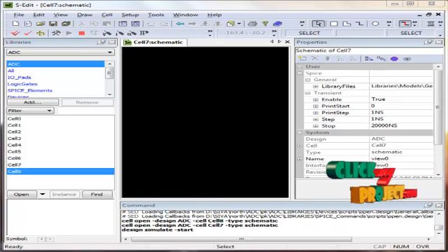Initially, the input digital word is given to a multiplexer circuitry. Depending on the logic value of each bit of the word, the multiplexer chooses the particular voltage to which the capacitor is to be charged. If the input bit in the digital word is logic 0, then the multiplexer chooses the input which is connected to the ground and the capacitor is charged to 0. If the input bit in the digital word is logic 1, then the capacitor is charged to Vref.